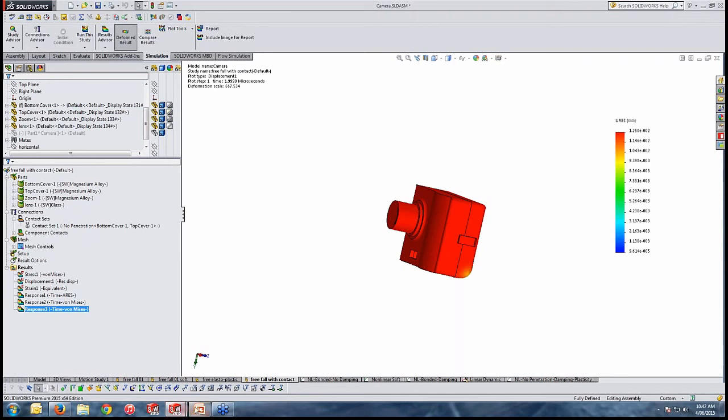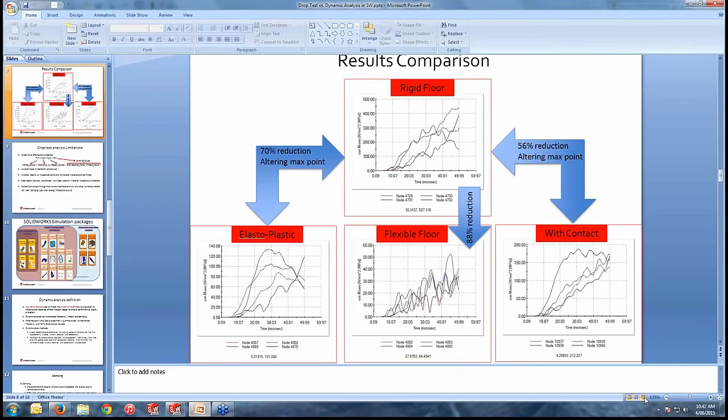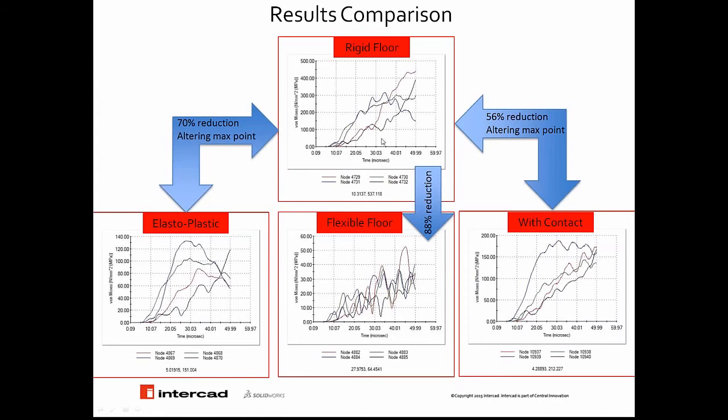What we are doing in this whole study is trying to get closer and closer to the real case. Now looking at the summary of what we have presented here, you can see the first case study, where we considered a rigid floor, our top magnitude of stress was recorded at around 400 megapascal at one point, and the other points are starting from 150 up to 350 here. One basic assumption, just a flexible floor, can reduce the magnitude of top stress down to 88% here.